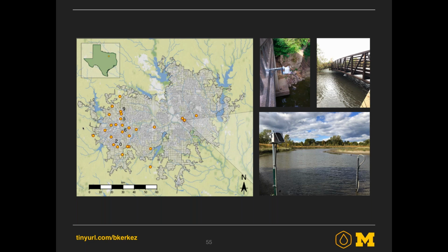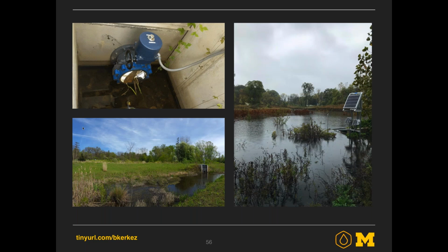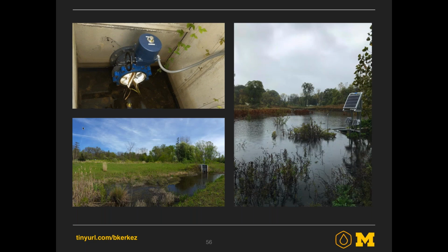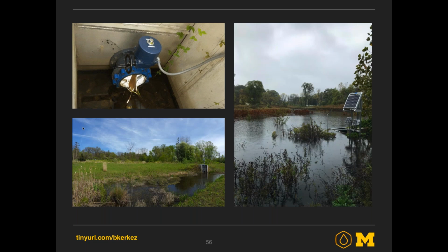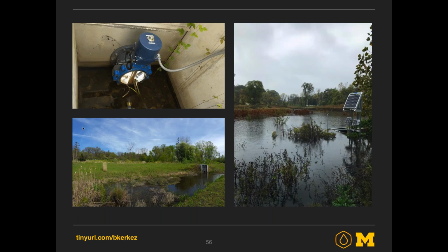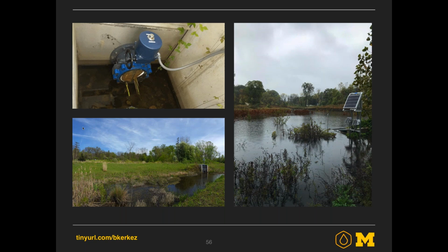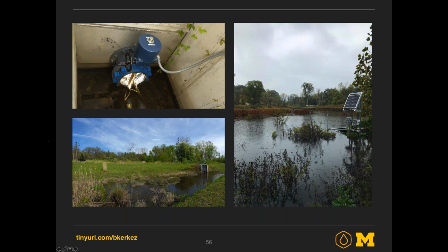But the thing that we've been pushing for a long time is the controls. So here's a picture of one of our valves. This is how you control a watershed portion. You basically take a valve that was designed for industrial purposes. It's a butterfly valve. It's nothing earth-shattering. It just doesn't exist on stormwater systems. And what we did is we figured out how to connect that valve to the internet. And we go into stormwater systems and we retrofit them.